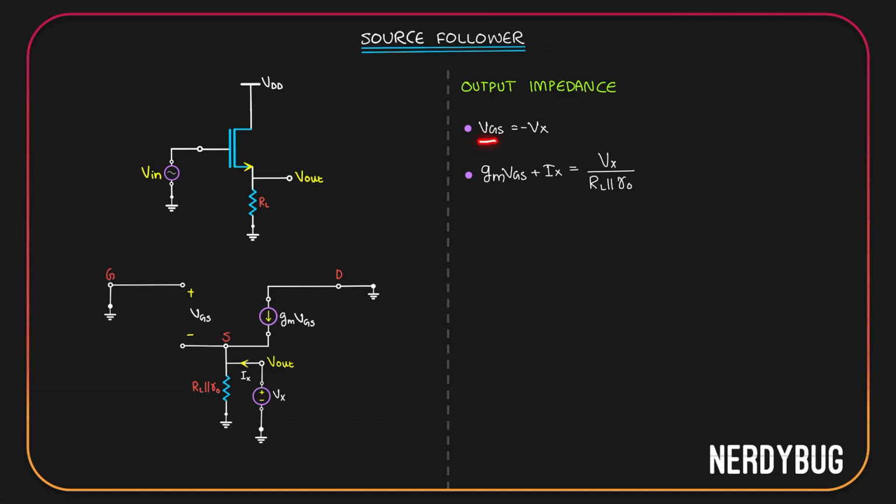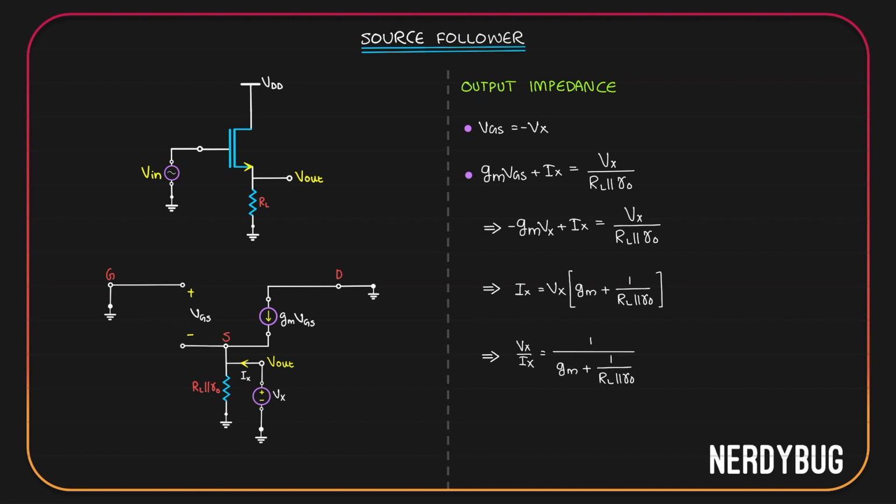Now VGS is minus Vx, so let's replace it over here. That gives us this. Both these terms have Vx in them. Let us combine them together. That gives us Ix is Vx multiplied by gm plus 1 by RL parallel to R0. What we need is output impedance, which is Vx by Ix. From here we can easily write it. It is 1 divided by gm plus 1 by RL parallel to R0.